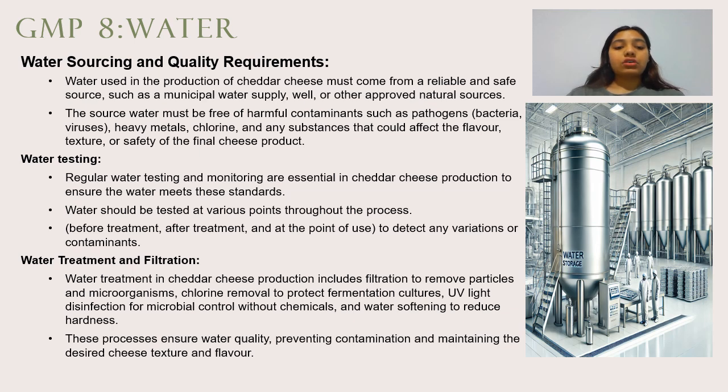Water testing on a regular basis is also important, and monitoring the water supply is essential in cheddar cheese production to ensure that the water meets the standards. Water should also be tested at various points throughout the process, and water treatment and filtration should be done regularly to remove particles and microorganisms, chlorine removal to protect fermentation cultures, UV light disinfection for microbial control, and if any chemicals are added in the water, water softening should also be done to reduce the hardness.